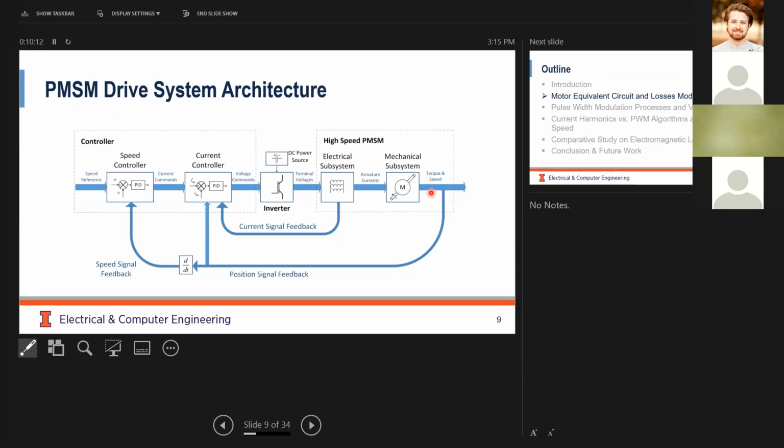So we need to analyze this problem to prevent the motor from being not workable. If the loss is too high, we cannot drive the motor with the inverter because the motor has a limited cooling capacity, right?